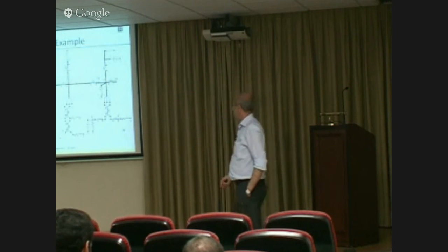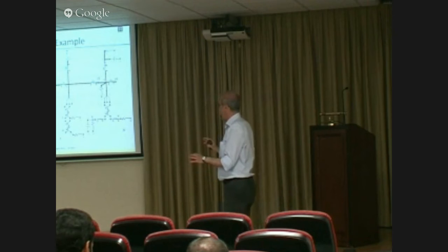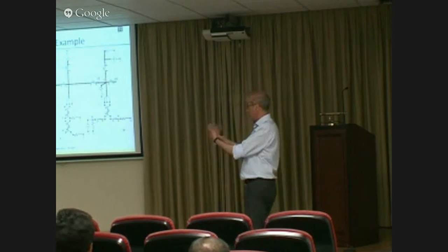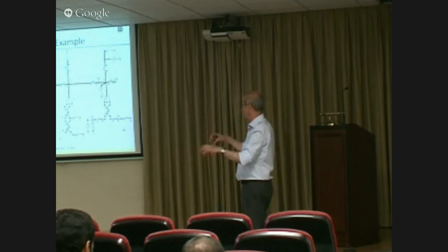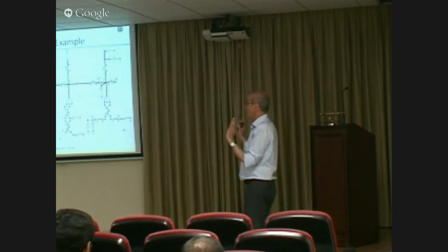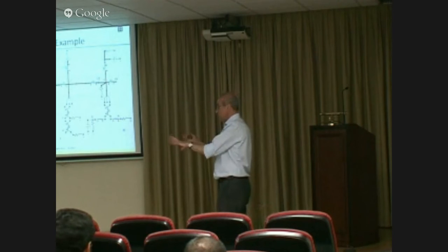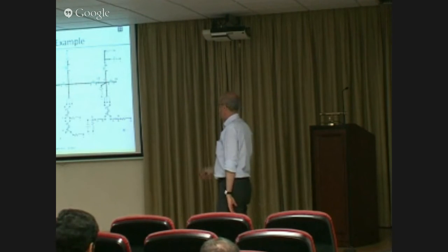So in this case, what we did is we actually applied the fault. We obtained the solution. Delta V jumps. The voltages jump in every bus. Then, using the solution, we injected it back into the admittance equation to obtain the corresponding changes in the injections, and this is what we got.